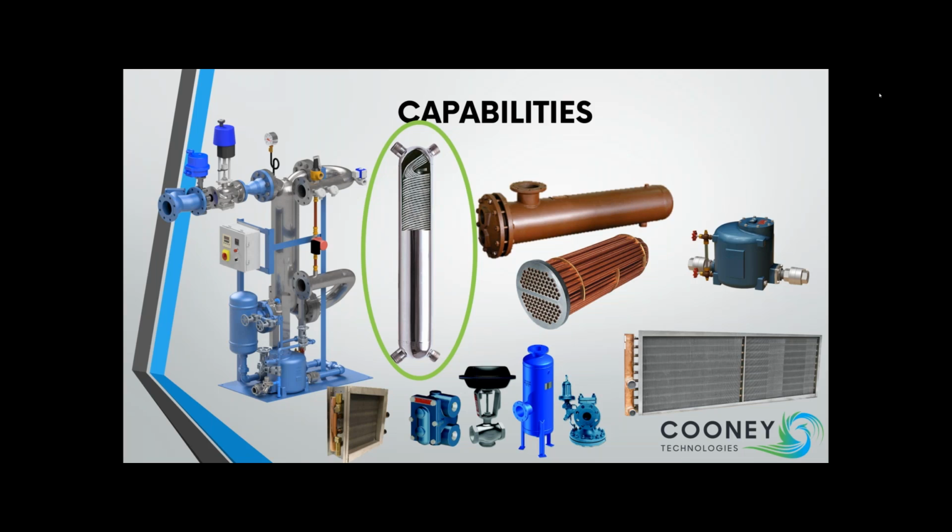Because, speaking for Philadelphia, it's a code requirement that you cannot dump any hot condensate down the drain at 140 degrees or more. So that's why these subcooled units are really important, where you could drop your hot condensate and subcool it down to, say, 110 degrees, 120 degrees. You could put your hand under it. You could just send it right down the drain.